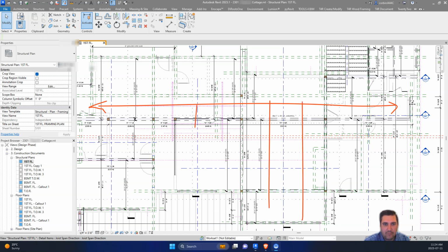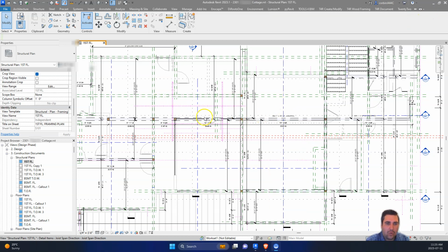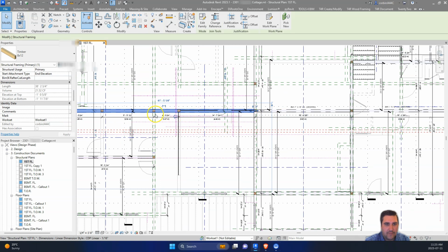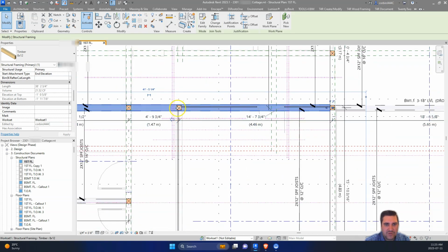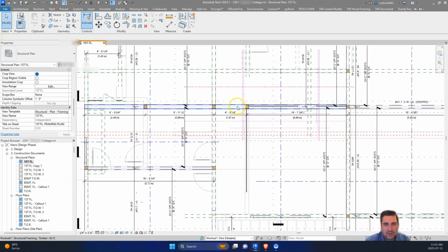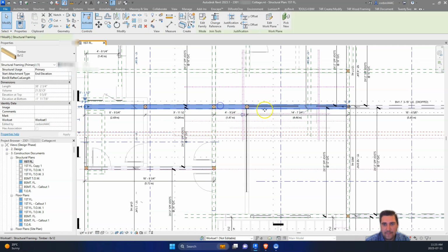But then, let me clear this somehow. But then it would be dropped in that corridor so we can have proper HVAC. So that's why we're going to do drop beams along this kind of area here. I don't think we need this post here, but I think it might help structurally. So I think we'll probably just keep all these posts here. So let's find the biggest span. The biggest span is 14 inches. It might honestly just make sense to keep the same beam size, but let's just look at it from a design perspective, and it might just be better to drop that.